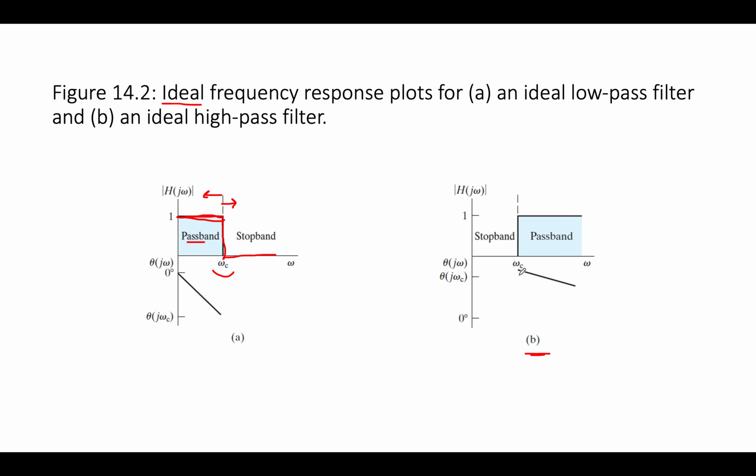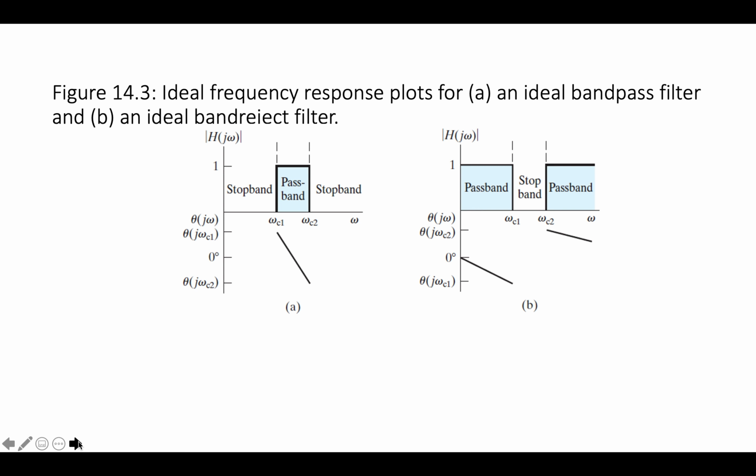Also, often used if for whatever reason you're going to integrate your signal. You don't want to integrate a constant, so you would want all those low frequency signals to be gone. So that would be your high pass filter. We use a high pass filter in my lab on the EEG system because it is not uncommon for the amplifiers in the EEG to do a little bit of low frequency drift, and so we want to eliminate that from our signal.